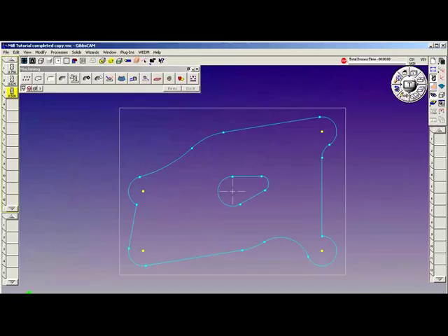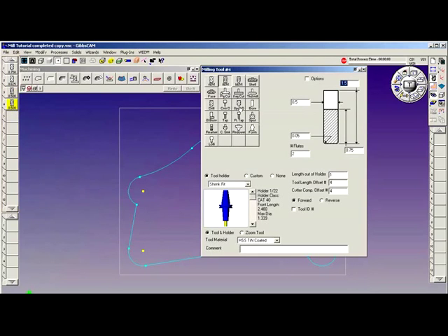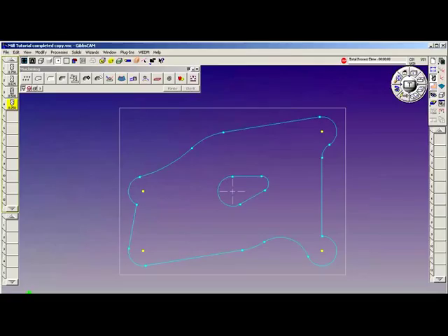All right, those are the tools that I'm going to use for machining the pocket and the contour. I'm going to build a set of tools to spot drill, drill, and tap 1/4-20 holes. So tool number 4 is going to be a spot drill, 1/4 inch diameter, and 90 degrees, 2 flutes, length out of the holder remains the same, and so the offsets have updated correctly.